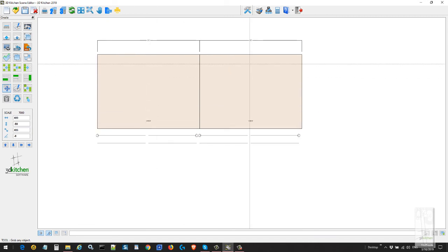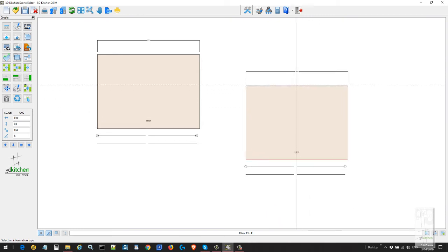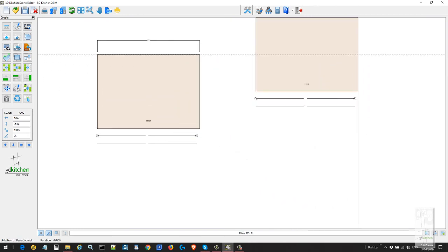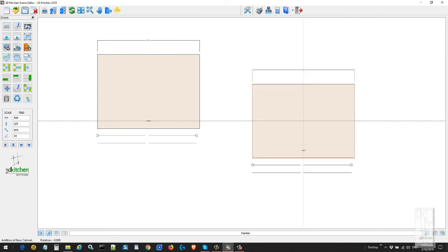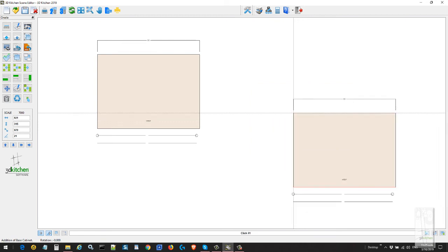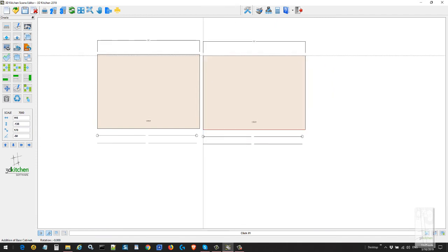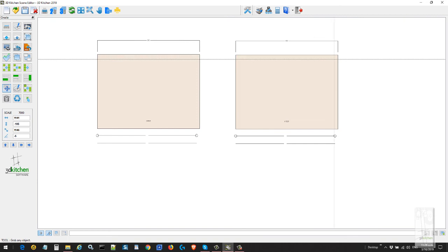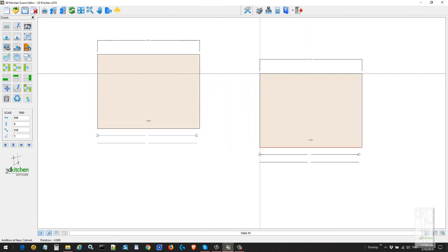So you can hold a cabinet by several positions. So back center, and then there's also each corner. So it's the center of every side and every corner. So you can see I'm cycling around those, and one in its dead center. So holding positions is important because that's how the program decides how to snap to the object beside it. So for example, you can't pick it up from the right hand side and attach it to this object. It won't attach. It'll just stay where you drop it. So you must hold it by that side.